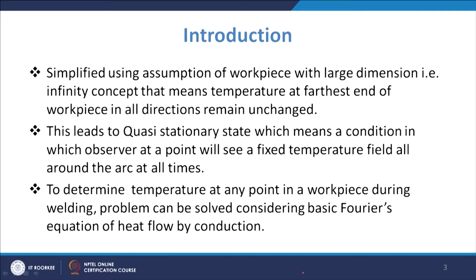You will have some assumptions, and further simplification using the assumption of a workpiece with larger dimensions. With a workpiece of larger dimensions the infinity concept comes into the picture, and that tells us that the temperature at the farthest end of the workpiece in all directions remains unchanged. If you take a point quite distant from the heat transfer location, the temperature there in all directions remains unchanged.